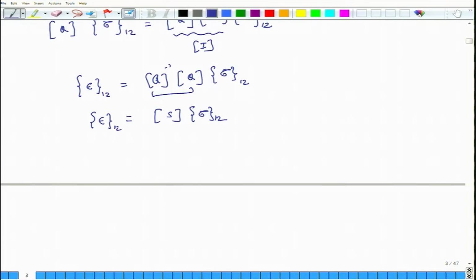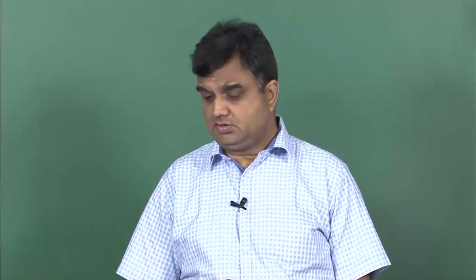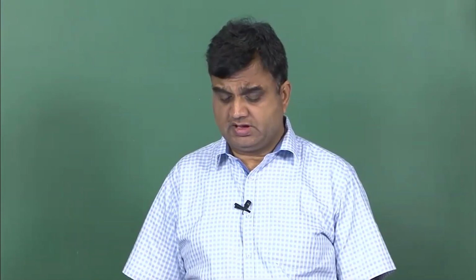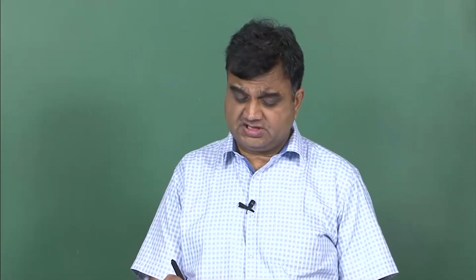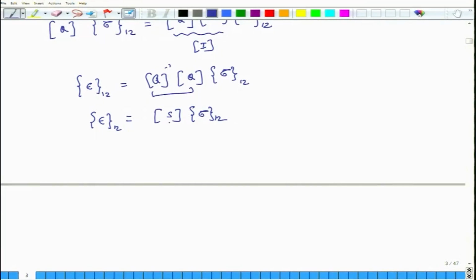So, if I know the stresses in a unidirectional lamina which is extremely thin, and if it is in a plane stress state, if I know the stresses, then if I multiply the compliance matrix with the stress vector, I can compute the strains in all the 3 directions. So, what we will do is spell out the relations between the S matrix and the Q matrix. So, basically it is just the inverse.